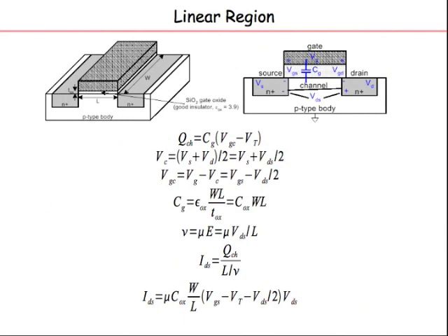And in a circuit, as we said, we have capacitors all over the place. You have to charge and discharge capacitors at the end of the day. So if you have very less current, it will take longer to charge and discharge capacitors, because you still have to charge up to VDD or ground. You remember, these are digital circuits. The voltage levels are the same.